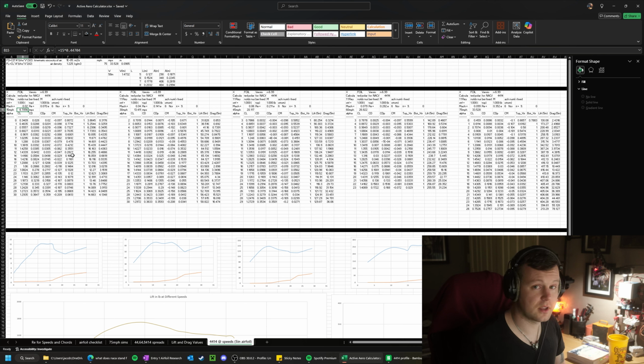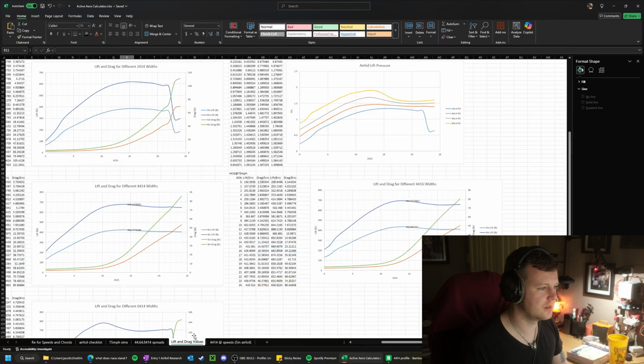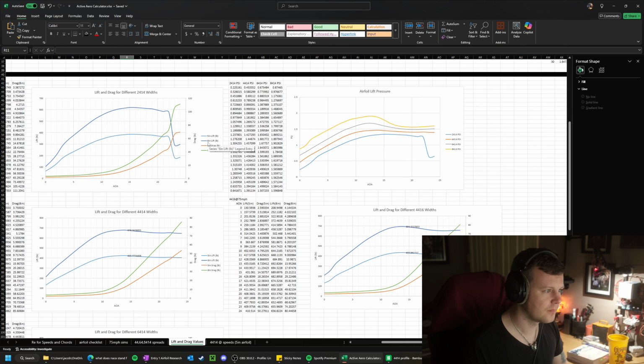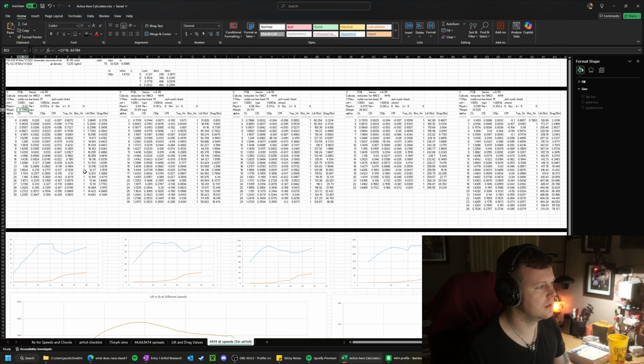So all the calculations are done in metric. I did change the end results to pounds for the forces just because my head thinks in pounds, but I like doing calculations in metric. I also used a 5-inch airfoil because I think the amount of forces we're getting with the 8-inch airfoil is much more than we need, especially if it's going to be a daily driver. I don't think we need to go with like an 8-inch airfoil. I think 5 inches is plenty, and so those are the numbers that I used for this, and I generated them at angles of attack between 0 and 30 degrees.